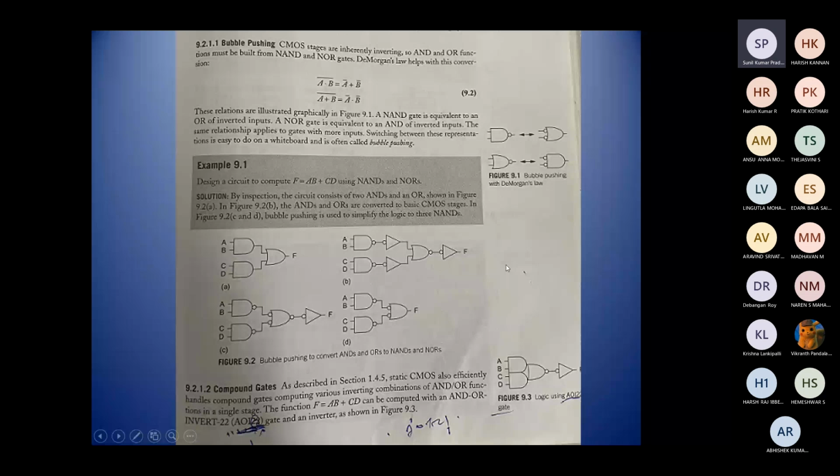any digital circuits. Now, compound gates are a way of representation where both simple logic gates and universal logic gates come together. So that is what compound gates are. So if you can see here, using this logic, this gives rise to the same output AB plus CD. So this is our AND operation. Then we have a NOR operation, and then we have an inverter operation. So if we compute this, we can finally get AB plus CD.